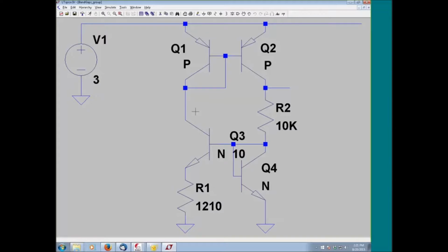And I keep coming back to this point of setup. Setup is the key here. Using the LTSpice EAGLE bridge is very front heavy, very front loaded. You have to make sure there's correspondence. And this is the key point here: correspondence between EAGLE's library and the LTSpice library. Any parts that you have in your EAGLE schematic, any models that you have, need to have a counterpart in the LTSpice libraries. So any part you use in your design, there must be a counterpart in the LTSpice libraries.